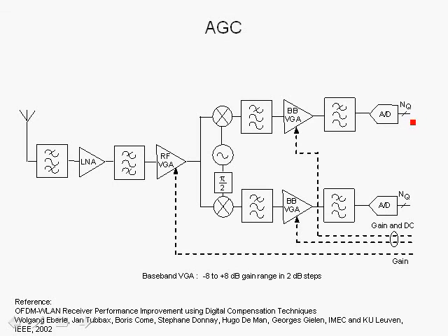So the baseband processor is continuously calculating the RSSI, or the average power at the output of the A to D, and if it exceeds a certain threshold, it realizes that the gains are too high. We have a high SNR signal, and it has to command the gains to start lowering. The first step is to lower the gain at the RF stage, and then continue to adjust the gains at the baseband stage in order to bring the RMS at the A to D output into a target RMS value.